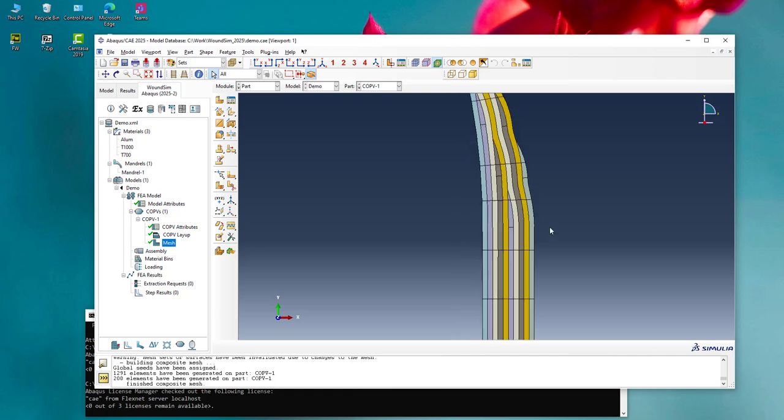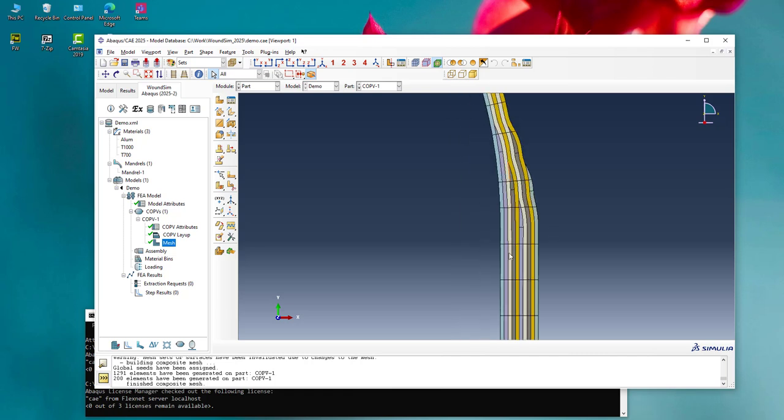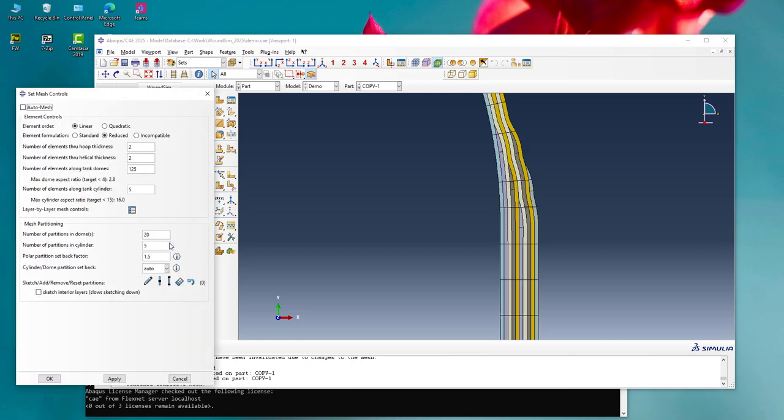All right. So the thing is, right around this transition area, we still have some oscillation. So this area we may want to mesh with a finer mesh. So let's see how we do that. Auto is what we've got it set to. That's the one that says, as soon as we find one that doesn't have any partitions in here, we're going to go ahead and mesh that with the coarse mesh. So let's instead set it back by some distance.